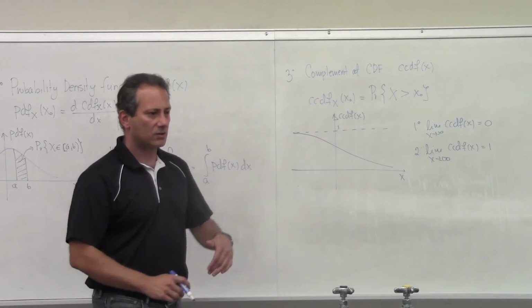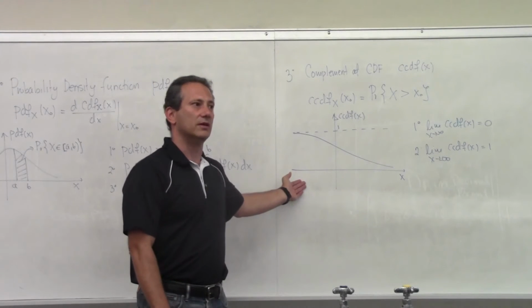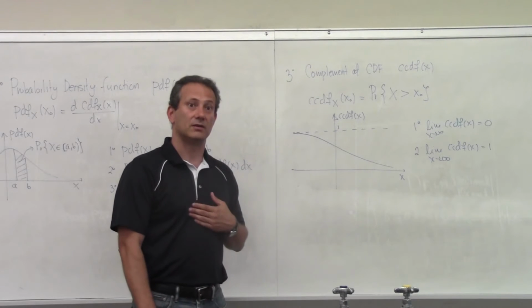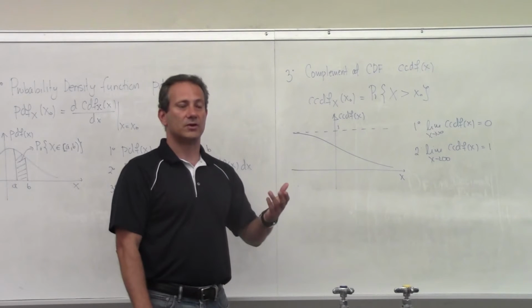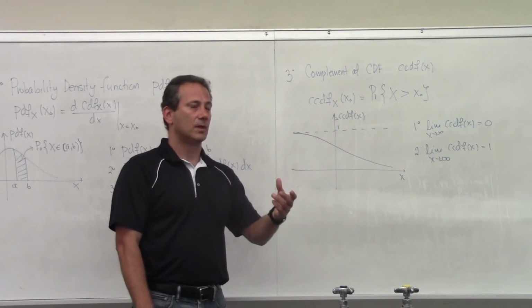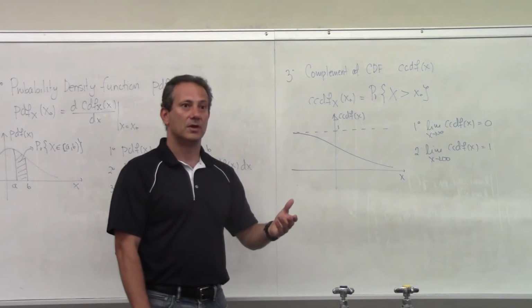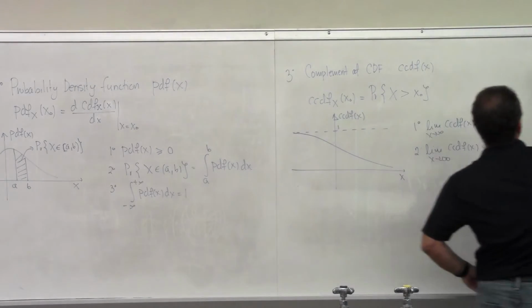Now, in satellite communication, we already kind of introduced CCDF. When did we introduce the CCDF? When we talked about peak to average power ratio, right? Over there, we said, well, this peak to average power ratio of this waveform at a threshold of 0.1% is, let's say, 5 dB. So what does that mean? This is exactly what I have here. So let me do that as an example.